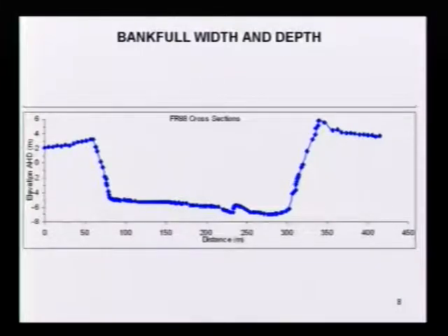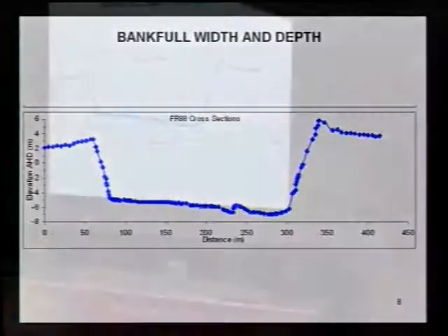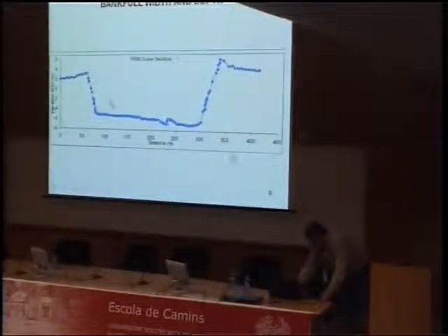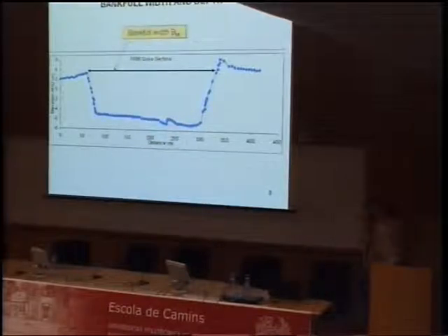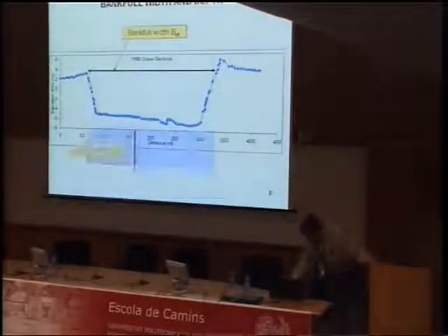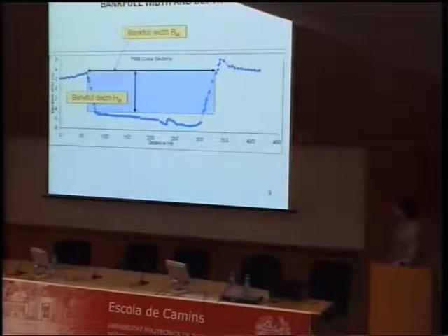And this shows one sample of many cross sections where we can see both the bed of the river, the floodplain, and also natural levees built on the river. You can see that the river is on the order of about 200 meters wide and on the order of about 10 meters deep. This is an approximate measure of bankfull width when we would start to spill significantly on the floodplain. Obviously, it will be measured in terms of the lower levee. And an equivalent rectangular cross-section with the same area gives us our bankfull depth.